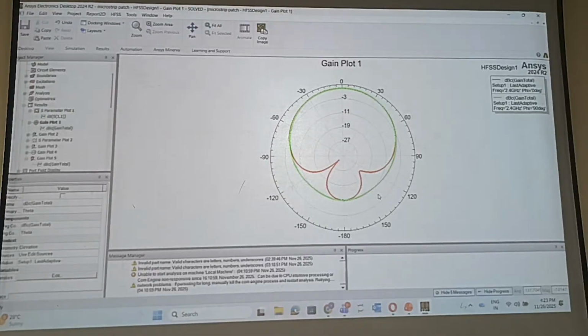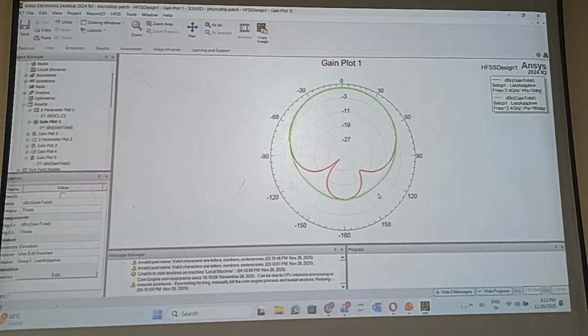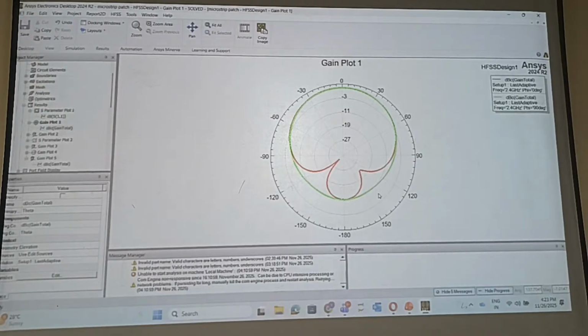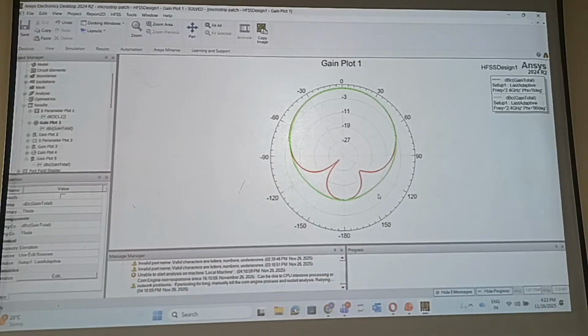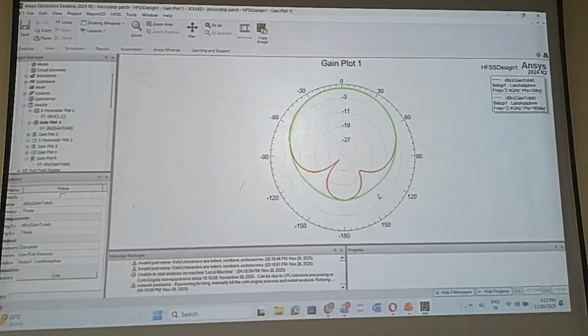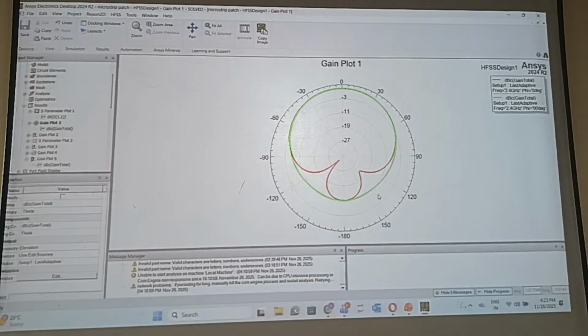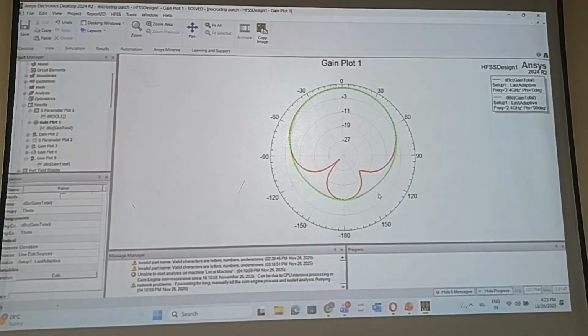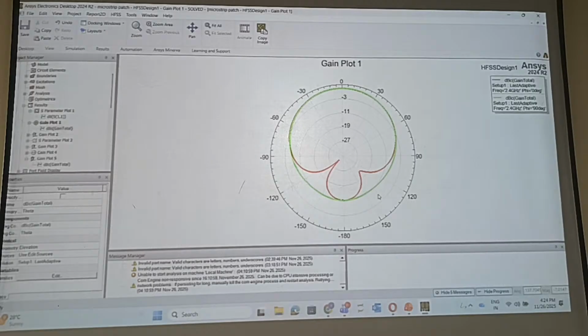Now in case of applying boundary condition, you have to select any slot and like that boundary condition towards the reverse direction. Whatever, reverse or forward, up to you. If you have selected like this, you have to select all slots like this. If you are selecting the arrow in forward direction, select all the boundary conditions in forward direction. Otherwise, mismatch will happen. I'll show that part.